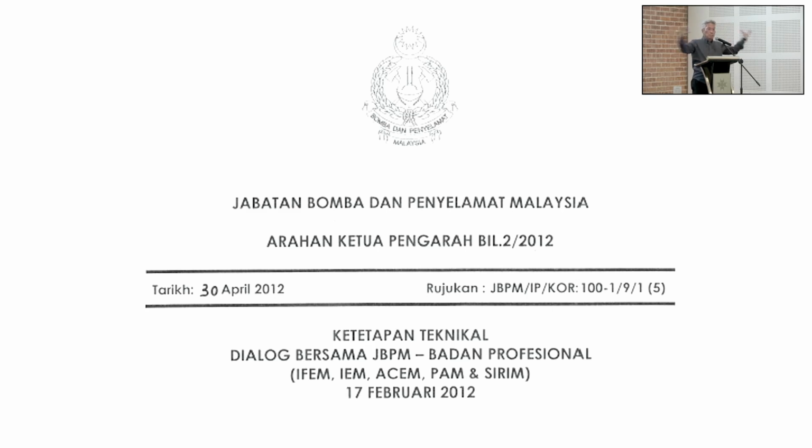Compartment wall, compartmenting limits of volumes that will dictate when you need sprinklers, where you need smoke spill systems, and where you will need other provisions in terms of active systems in the 10th Schedule.